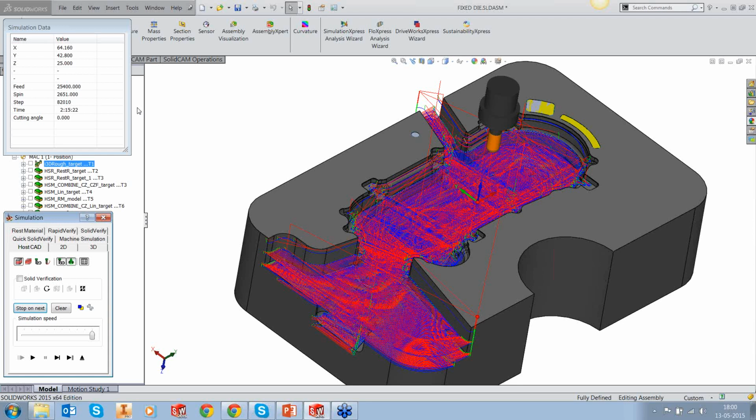However, assume the part is pretty hard, 48, 50 HRC, then this will not be valid. The roughing itself could go beyond 4 or 5 hours. In such cases, you need to identify areas or pockets which could be handled by iMachining to cut down the time and also save on your tool life. And then the remaining area, you need to cut using HSR.